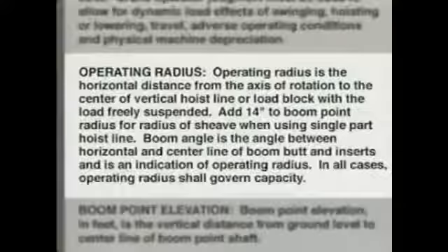The corresponding number of line parts must be used for the maximum load selected. That number is based on the catalog breaking strength of the rope with a recommended safety factor. The load line and whip line specifications apply to the wire rope that's used for the main hoist and the auxiliary hoist. These specifications must be met before the capacity chart can be used.